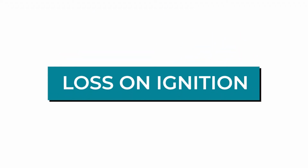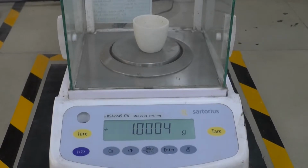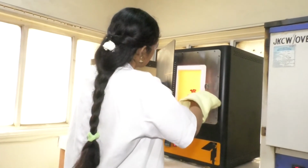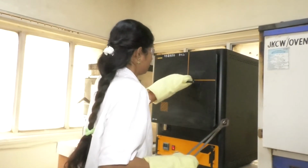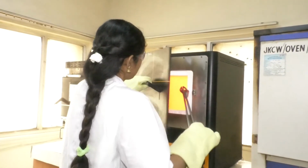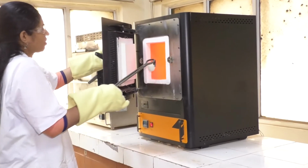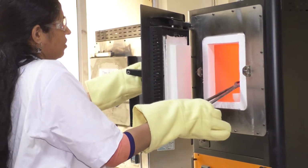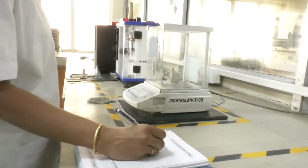Loss on ignition. To determine the loss in mass percentage of cement on ignition, take 1 gm oven-dried sample and heat it in a weighed crucible by placing it in a muffle furnace at 900 degrees Celsius to 1000 degrees Celsius for 15 minutes. Now cool and weigh the crucible with sample. Again heat for 5 minutes in the muffle furnace and reweigh. Record the loss in weight as the loss on ignition and calculate the percentage of loss on ignition.